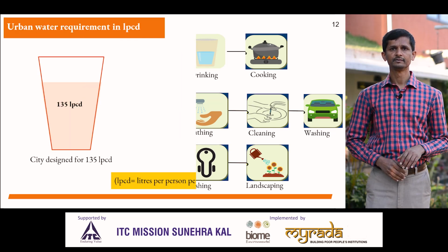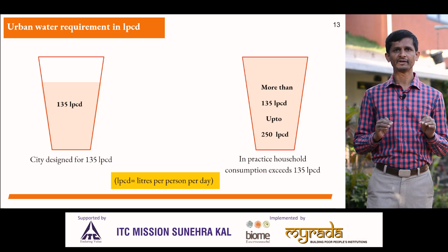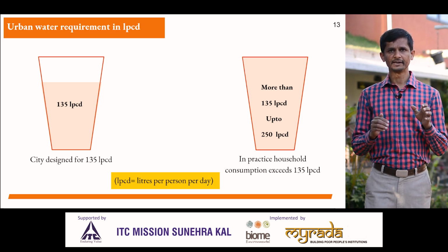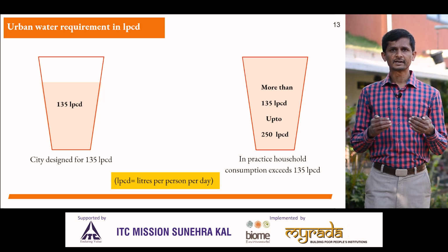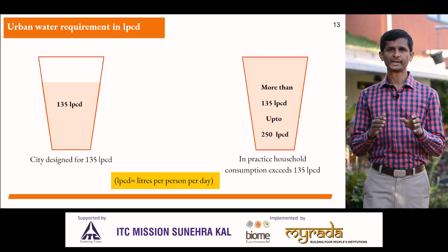fresh water. In urban areas, per person daily water demand is designed for 135 litre per capita per day. But we have observed that the consumption is sometimes up to 250 to 300 litre per capita per day.